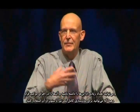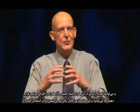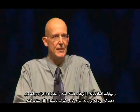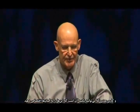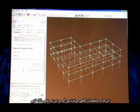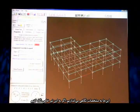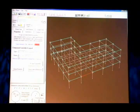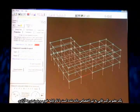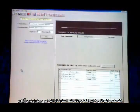Then you can take a number of these and put them into a compound component, which you can use to model a complete beam or a complete column. And then what you also do is assign them to elements. Let me just illustrate that while I'm here. If we look at properties here, if I look at this particular beam, it's been assigned a frame member compound component, and the name of it is perimeter girder with no releases.